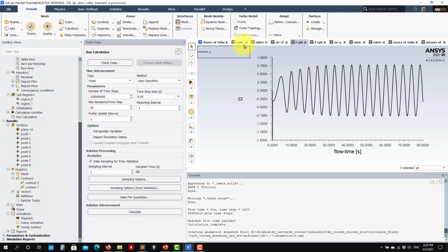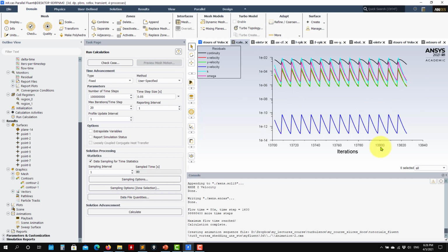So at this point, you can see the last 1,000 iterations of your convergence monitor, to see whether they go down or not. What you are looking at here are your initial residuals. You then have final residuals that always reach convergence. This is the initial, and this is not a problem. This is just telling you that your case is fully steady.